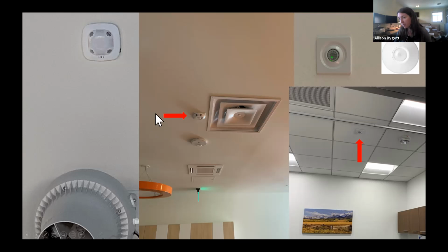So these are different pictures from out in the field. These are occupancy sensors. There are different brands and they all have different nuances. This guy right here used to be my nemesis because these are indicator lights, but in this brand, they don't light up unless you have a little remote that lets you put the sensors in test mode. So I could see them in the ceiling, but I couldn't tell if they were working unless I had a fully unoccupied building and could wait for the lighting to time out from the timeout period.